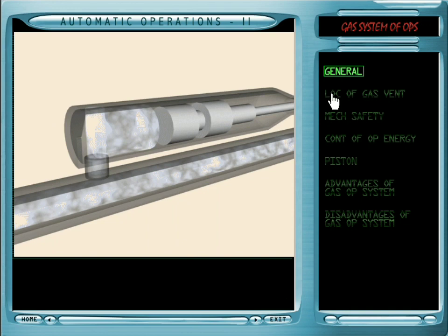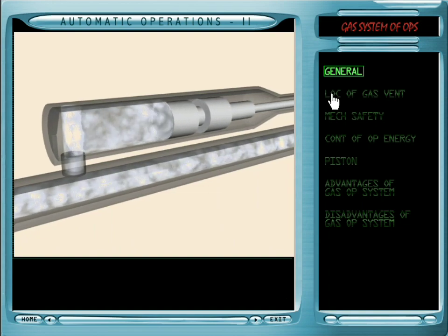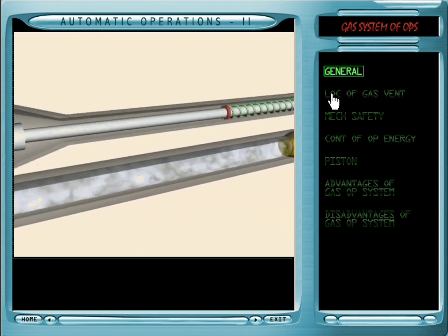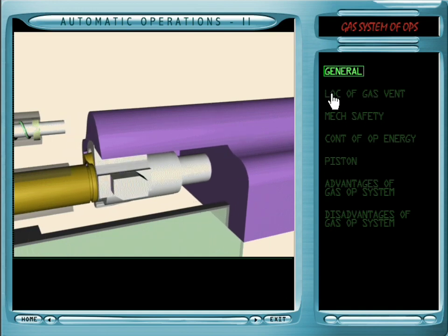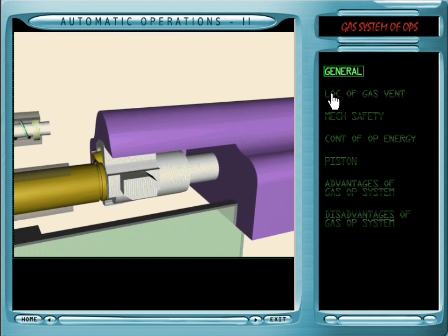The gas works on the piston head, which strikes the slide carrier, and it moves back, thereby unlocking the breech block and the moving parts. They also move back freely, thus carrying out extraction and ejection.